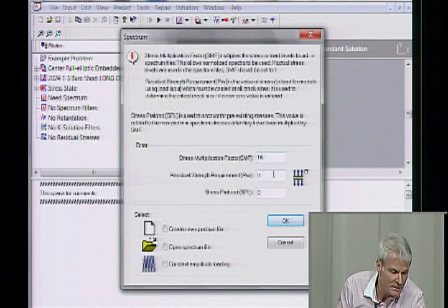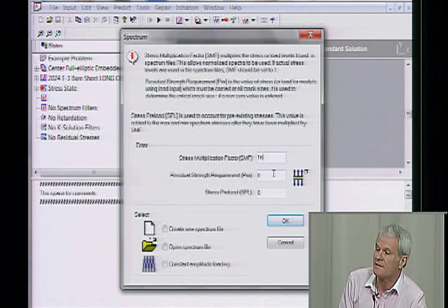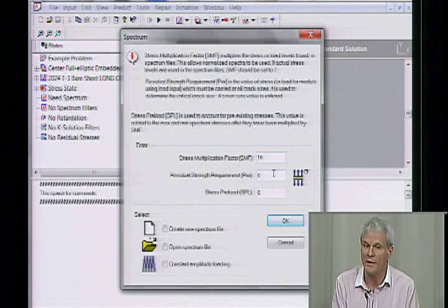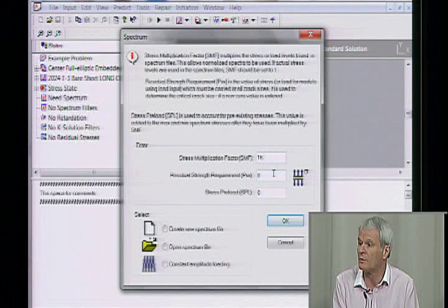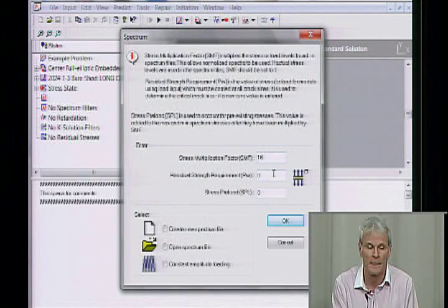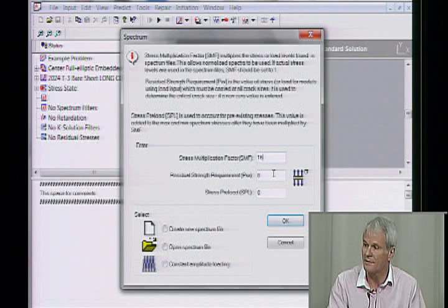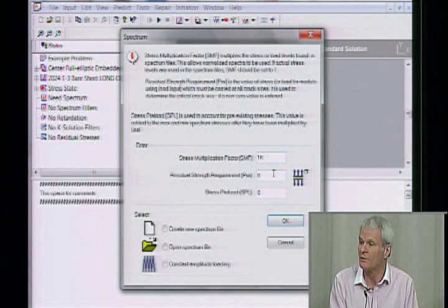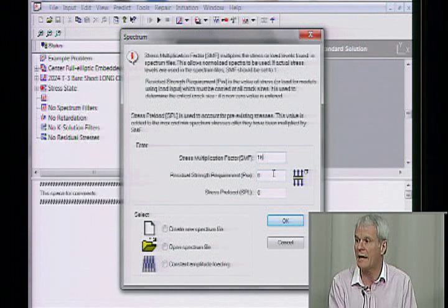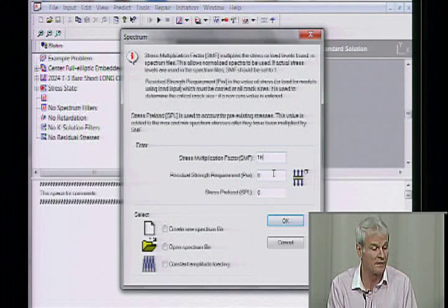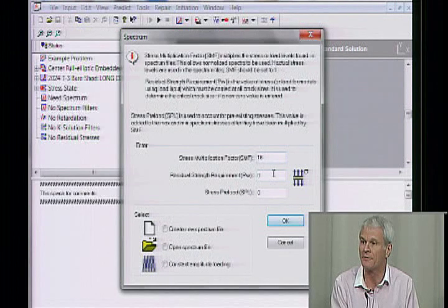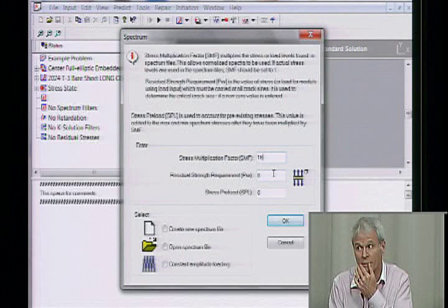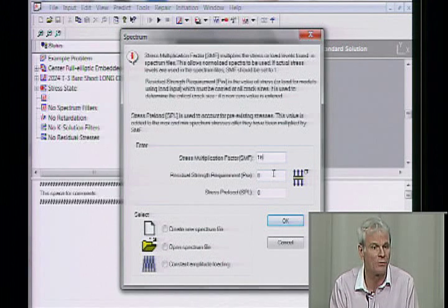And we have here the ability to look at a residual strength requirement. Let's say you had a structure with some kind of variable amplitude loading spectrum, and you had some maximum that you would have to maintain at some point. But you may not know when that maximum is going to occur. AFGROW goes through the sequence of loads in the spectrum in order, but if you didn't know when the max would occur, you'd want to check at every step to see if it happened now, would it fail? So that's the significance of this. If you put the stress value here, that tells AFGROW to check every step of the analysis to see if that load would fail you, even if your applied load at that moment might not. Does that make sense? That's what that's for.